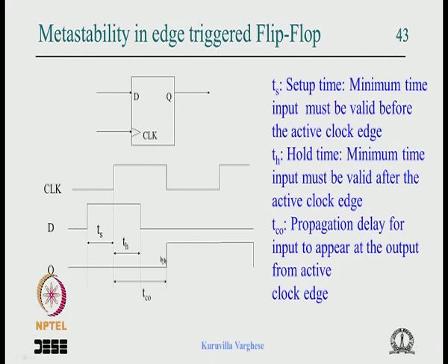So what I am saying is the game in a gist, so that I don't leave some curiosity, as if I say accept it as it is and you don't know where it is coming from, suddenly a magic. I just want to tell you that when the clock period is low, the master latch will be in the transparent mode. Okay. So the master latch is capturing the input, but the latest it can capture is some time before this is getting cut off.